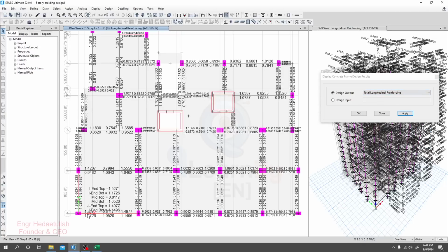If you come here, you may see this is actually nothing but the total summation of longitudinal reinforcement and torsional reinforcement. So I'll take this option as the longitudinal reinforcement, but as this is a big span and we are getting more reinforcement here, we may ignore that beam when making the same grouping.